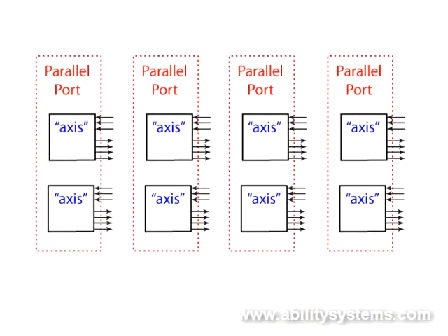Indexer LPT refers to each axis with a letter designator: A, B, C, D, E, F, G, or H. Groups of 2 axes are physically presented on each port connector, so one port may support axis A and B, another supports C and D, and so on. The signal set is called an axis because it is typically associated with a geometric axis of motion.